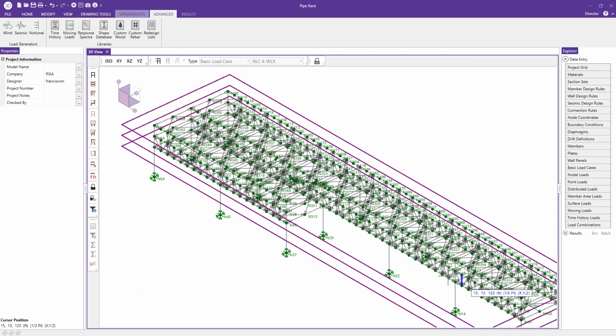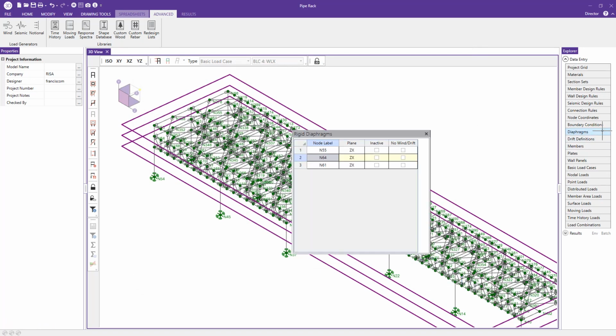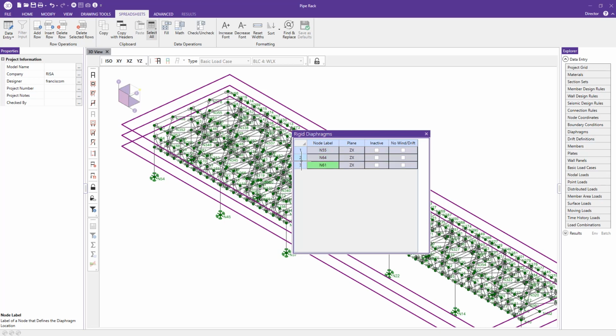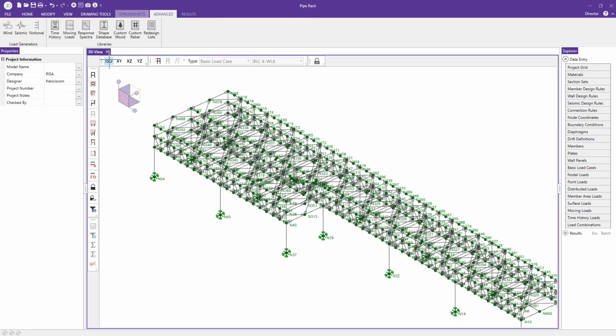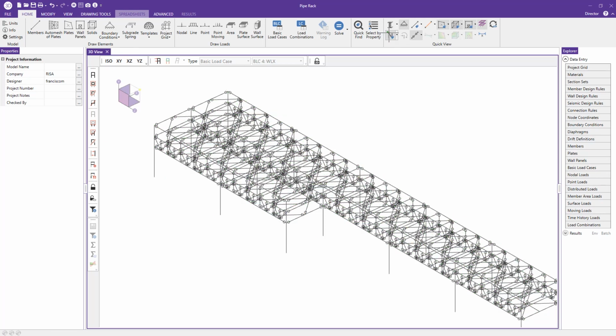Okay, so now as I promised, I'm going to jump back and delete those diaphragms because, again, we don't truly have an infinite plane of rigidity. We don't really have a true diaphragm element modeled. So I'm going to go ahead and delete the selected rows. And then what I can do now is I still have that 7,000 value in my head.